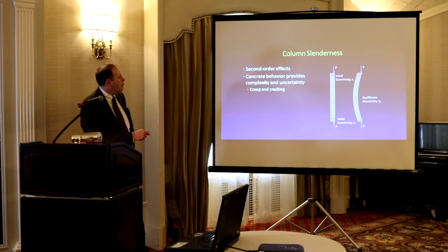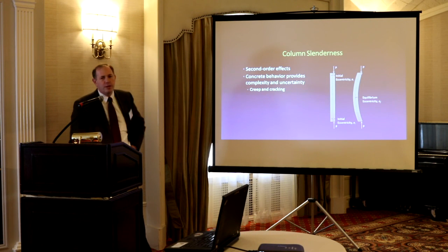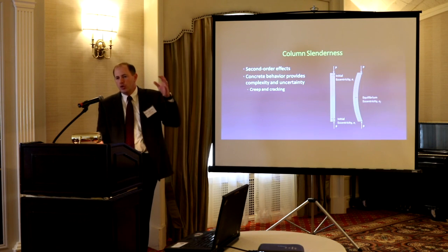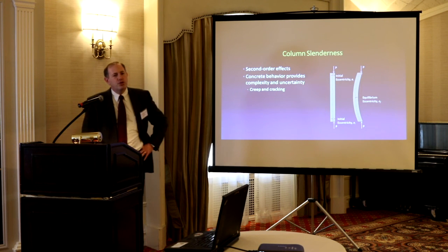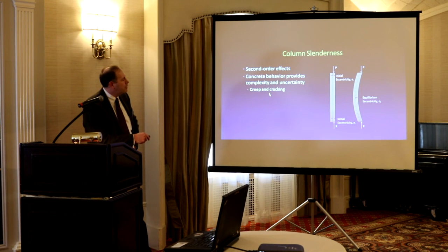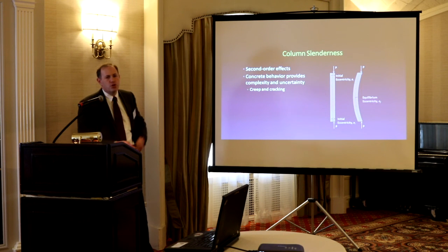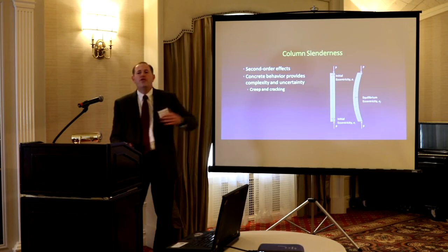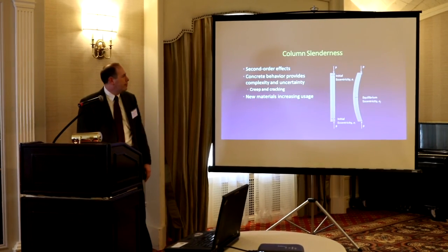Because of this, we also pick up something called creep. And creep will have second order effects. So I don't have that issue with steel where I'm shortening as I go. So those are some of the complex pieces. And one other thing just to mention about cracking, it's not just uniform cracking. Where there's higher forces, you get increased cracking and decreased cracking at other locations. So there's varied amounts of cracking throughout the member.